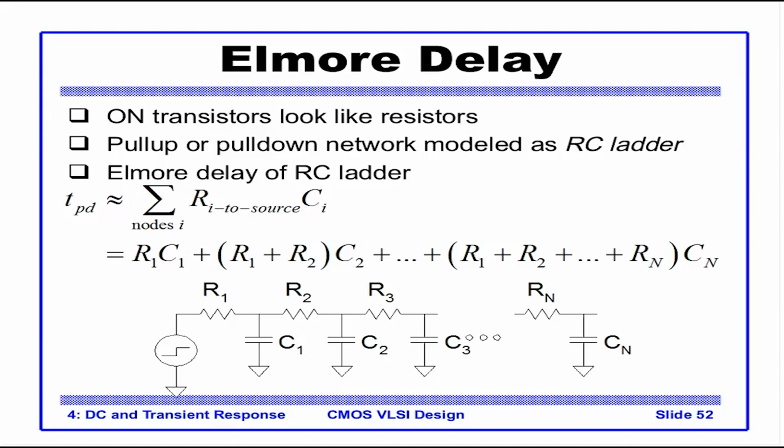This is a formula proposed by Elmore, called Elmore delay, to give a very quick calculation of a delay. The numbers will not be accurate, but using this you can compare two designs. That analysis would be accurate at least. The absolute value of delay doesn't matter. That's why we say that propagation delays can be represented by this formula. This is a very popular formula to compare multiple designs.